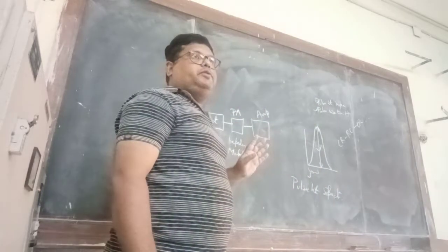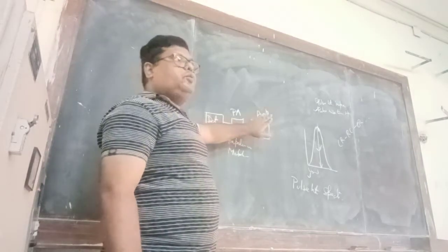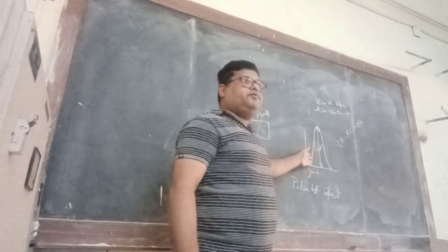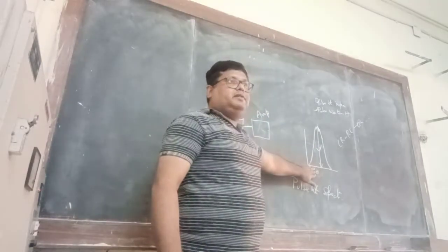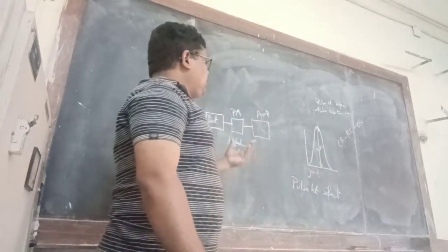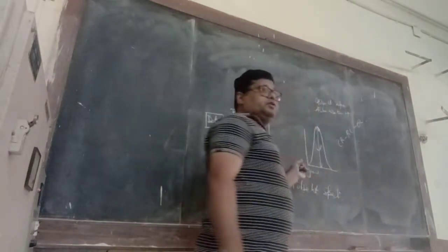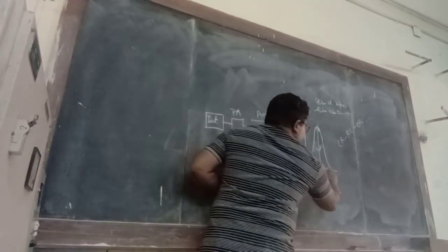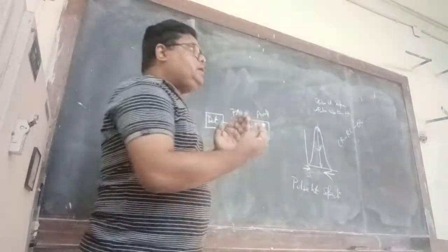So this is what we will be doing. This part is done over here in the amplifier. What the amplifier does is it shapes the signal to the Gaussian form, okay, and you see the rise time is retained. Only the trailing time has been shortened. The pulse shaping has been very nicely done, and so two things have been done. One, the signal has been shortened.